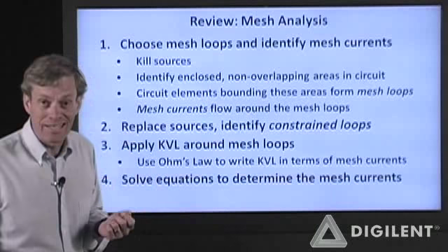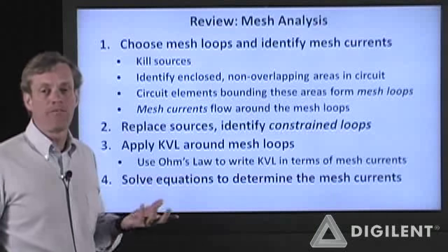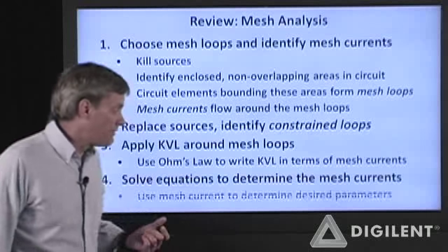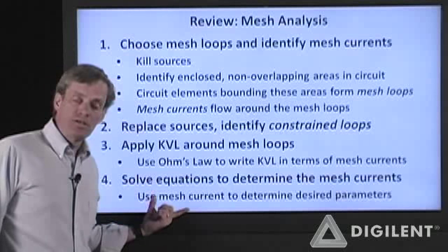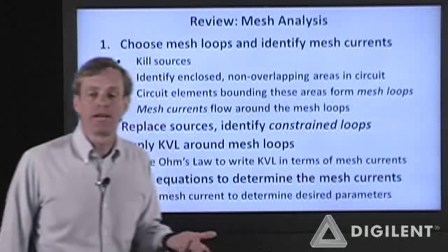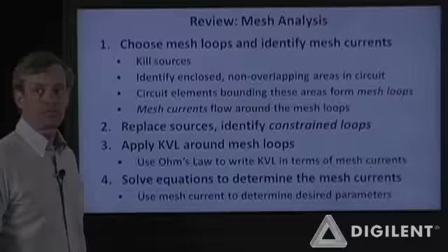When I solve those equations, I can determine the mesh currents. The mesh currents, as I said before, are not necessarily a physical current in the system. You can use those, however, to find anything else that you need to know about the circuit. So use your mesh currents to determine any actual desired parameters that you want.